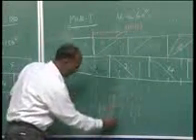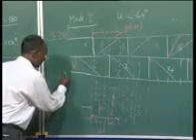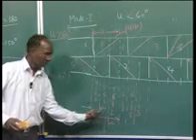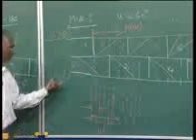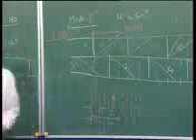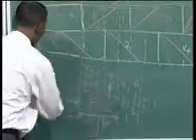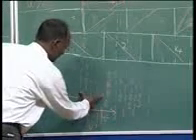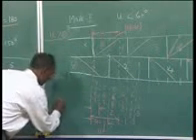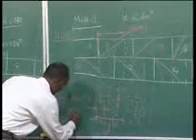So, you can see that this period, when the 4 valves are conducting, it is your U minus 60. Means when 4 are conducting, always when 4 are conducting, it is U minus 60 degree. Now, I want to know what will be this your 3 valve conduction period. 120 minus U, because the total is 120. Already we have gone for this 60, this 60 minus this 60. So, it is 120 minus U, means this is 60 minus U minus 60, here means it is 120 minus U.